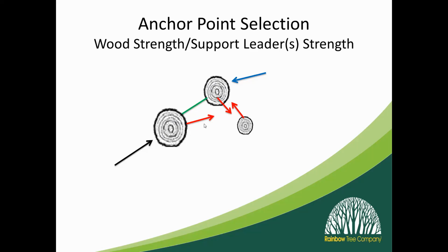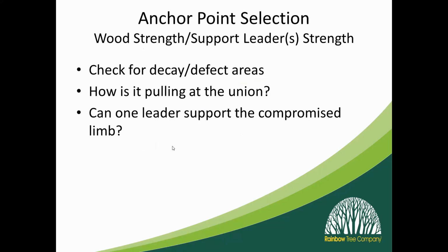And things change. So the best thing would be doing that triangular configuration to gather in some of this. So we're not 100% loading onto this side or 100% loading onto this side. We're splitting the load between there. And then having this connection here, we'll make sure when it pulls, it's not going to pull perfectly in line. It's going to pull more, kind of bisecting that angle a little bit, so it's not going to be perfect. Obviously, there are trade-offs, and not every tree is set up in a perfect world.